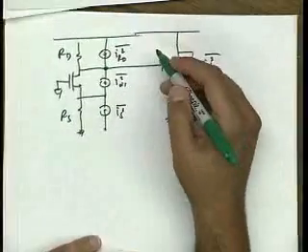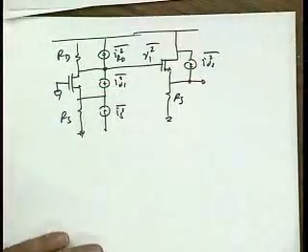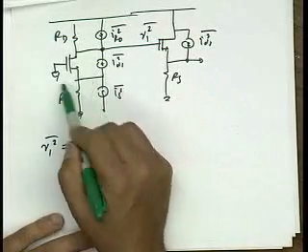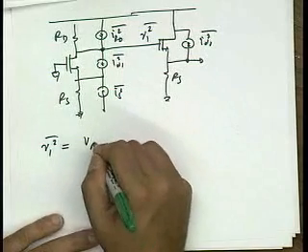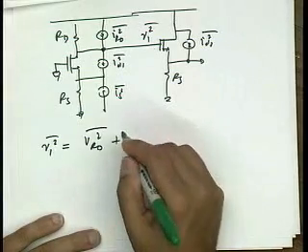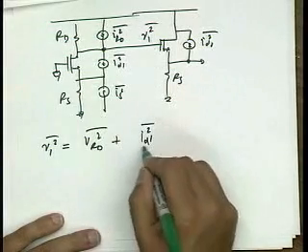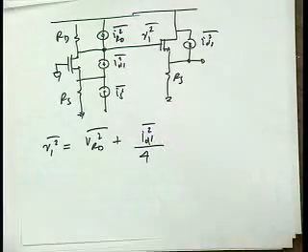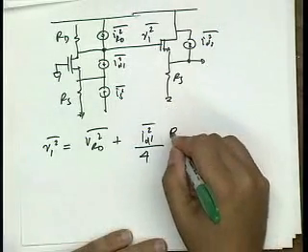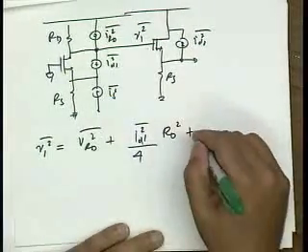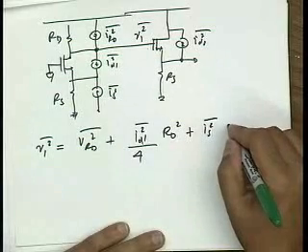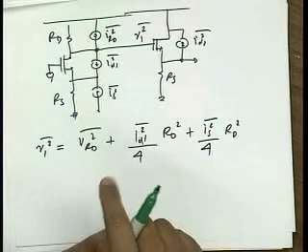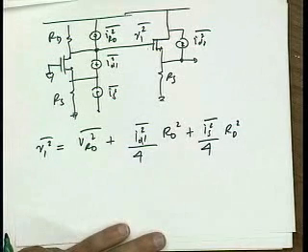Okay. So let me calculate V1, the noise over here, based on everything I've learned. So V1 is basically, if this is a high impedance, is just going to be the noise of RD. So V_RD, that's simple. And then it's going to be the noise of this guy divided by 4, right? Because I have 1/(1 plus gmRS). gmRS is 1, 1 plus 1 is 2, 2 squared is 4, times RD squared. That flows into that point there. The noise of IS is basically also going to be 1/4 RD squared, because it's (gmRS) squared divided by (1 plus gmRS) squared, and again I have a match.